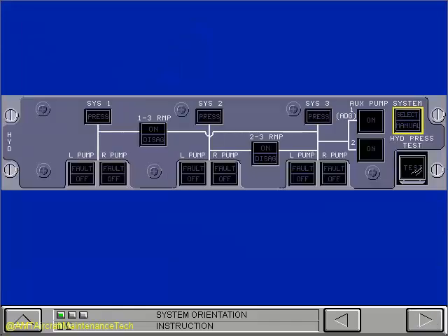The hydraulic system usually operates with the HSC in the automatic mode. When the HSC is in the automatic mode, the system select switch light has no lights on. When the system is in the manual mode, the manual part of the switch light is on. The hydraulic pressure test switch light does a test of the auxiliary pumps and the reversible motor pumps. We will not talk about this switch light at this time.